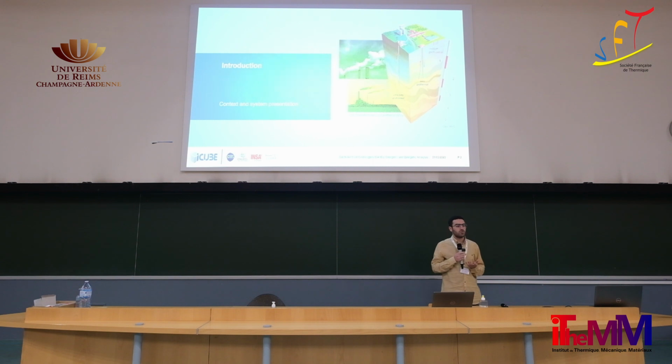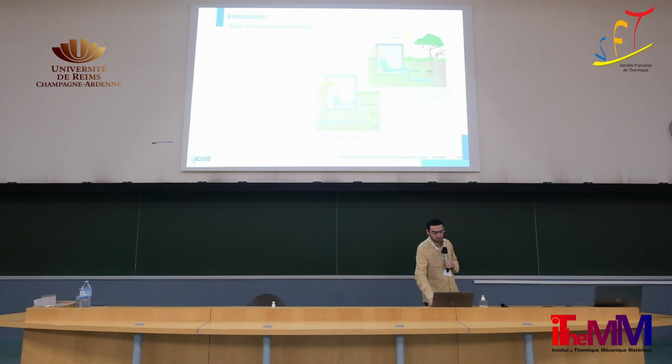They are a kind of shallow geothermal system. It's a simple heat exchanger buried under the ground. It uses air as a heat transfer fluid, and the air enters from one side, as we can see in the pictures. It gets heated or cooled by the surrounding soil, and then it is either used directly inside the building or it is further processed using auxiliary systems. The Earth exchanger is a passive system that decreases the amount of energy used and can thus decrease CO2 emissions.